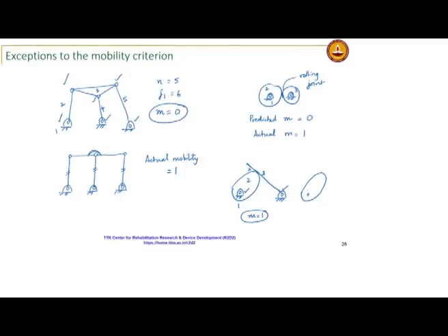Suppose the same thing I change the structure. You know, I do not want too much wear on just one part of this follower. Okay. So, I modify that to say that I am going to have a roller here instead of just this link directly in contact with the cam, okay, because the roller will keep spinning and I will have different points of contact.